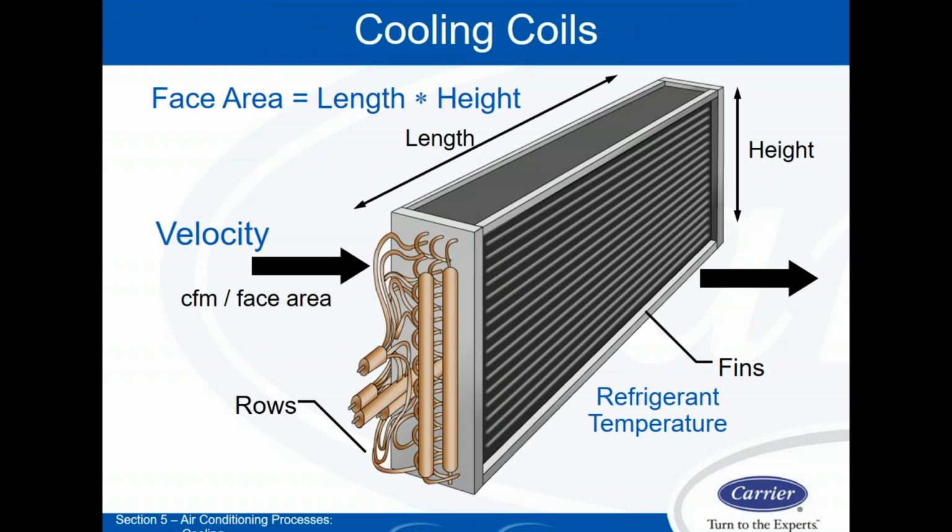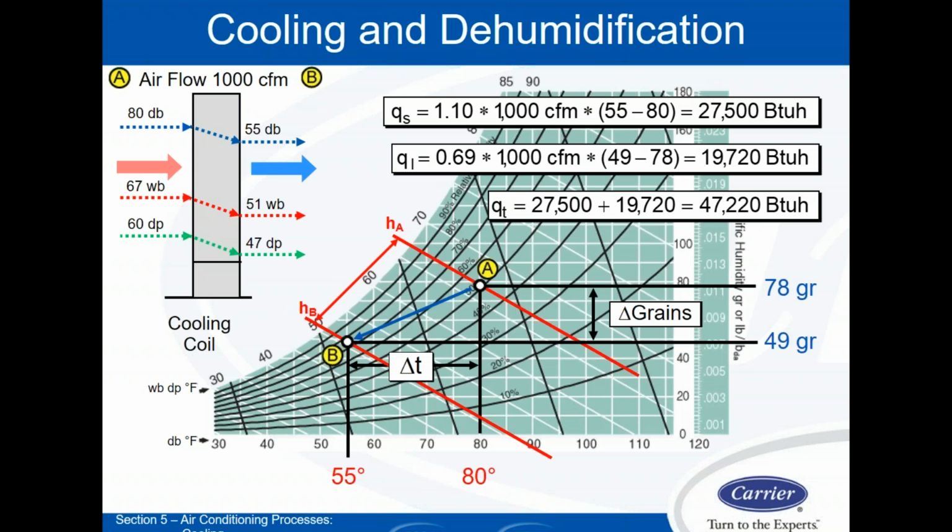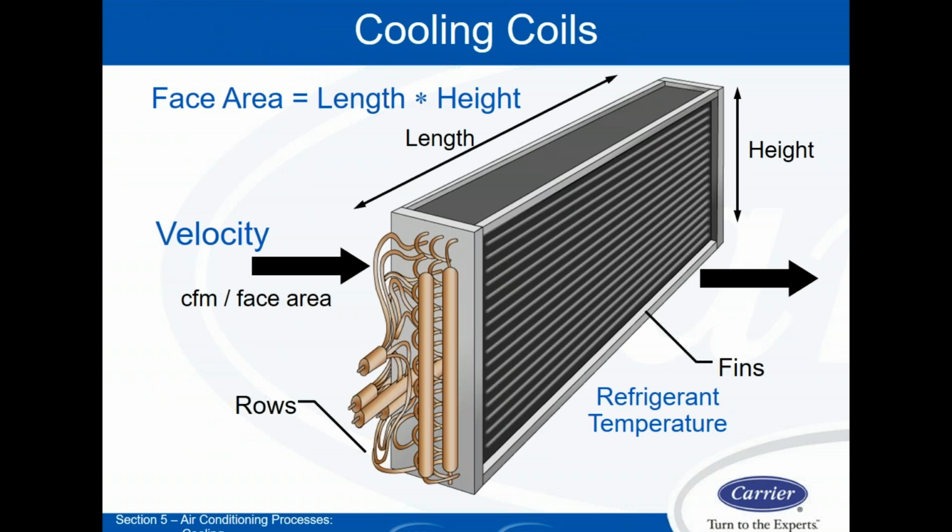All right. So we do a load calc for a project. That determines the BTUs that we need for sensible and latent. We use that to figure out the CFM of the air handling system that we are going to be dealing with. By the way, I should have mentioned here, when I said that example was 472 CFM per ton, that's if I had the sensible and latent together. I'm going to do it based off of the sensible. I'm going to size my air handler CFM off of that. So in that case, it's 275 CFM per ton. So it just depends on what we're looking at too.